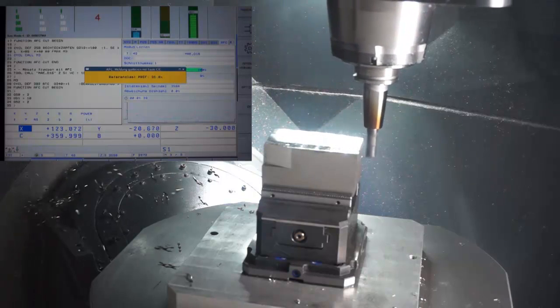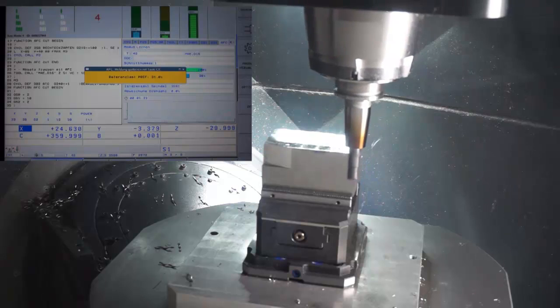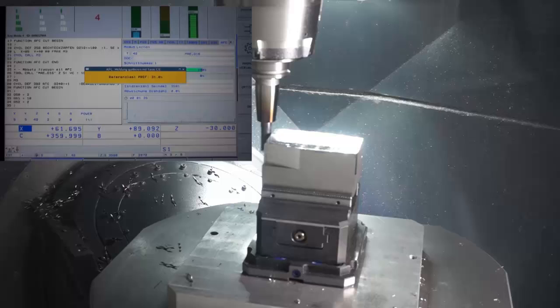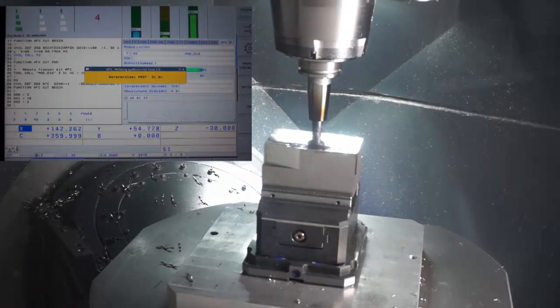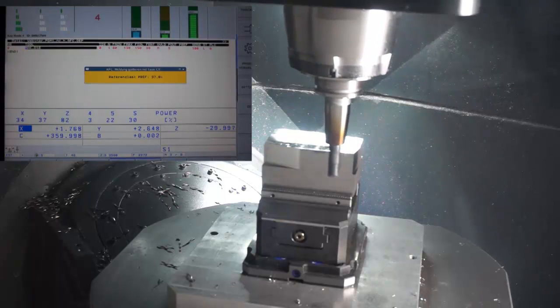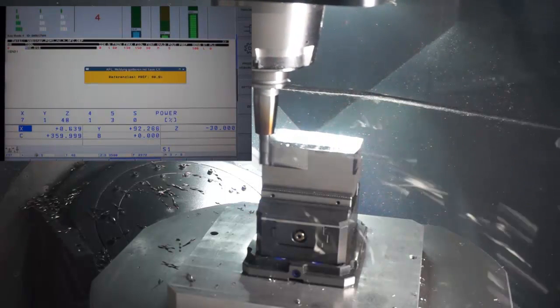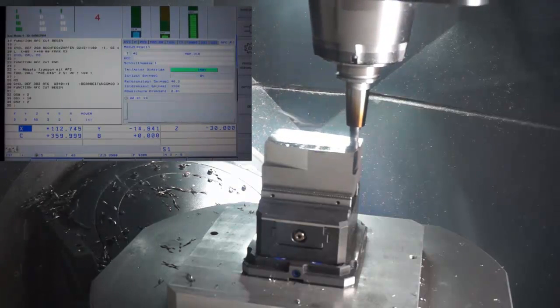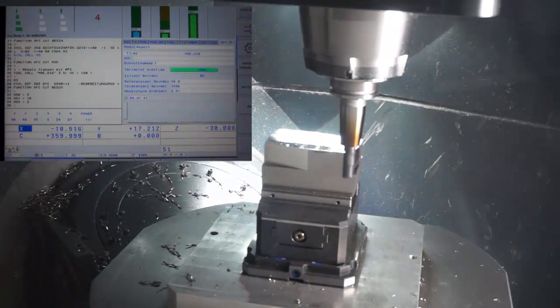We go to the AFC table, and soft key, and go to exit learning. So you can always stop learning manually by the soft key in the AFC table. Here you see the AFC table, and then you can say stop learning. And now you see the behavior of the machine.